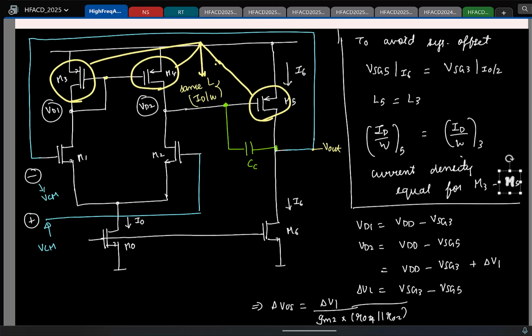Cool. So again, the bottom line of discussion should be this. Anytime you have a high gain op amp or an OTA like this, the bias point will be set by the global negative feedback you have around this guy. So even if it's a unity feedback, if this is at VCM, this is set to VCM.